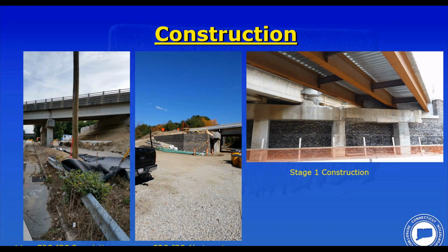That can be done with simple plate compactors. Very easy work, not a lot of big equipment. Once you start building the bridge, we're using blocks here that can be installed by hand, so we're not looking at heavy equipment. So we could build this entire abutment, I should say a majority of this abutment, underneath the existing bridge before we start closing the bridge upstairs and going to stage construction.